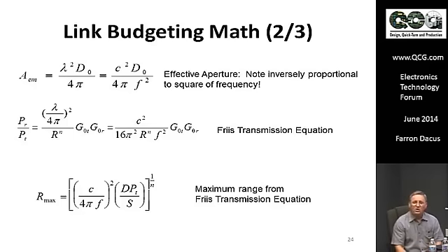One of the things that was always kind of striking to people in short-range radio is that the public really adopted 2.4 gig because everybody thought 2400 megahertz is better than 900 megahertz because it's a bigger number. But the frequency aperture is much better at 900 if you can use it. It's about 10 dB better. So everything else being equal, you got 10 dB more link budget to stay at 900 instead of going up to 2.4.